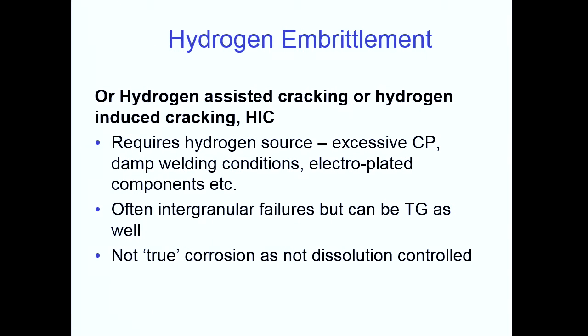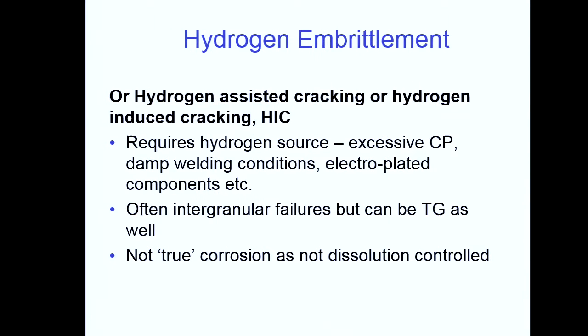And hydrogen is quite a tricky sort of material to deal with. It's colourless, it's odourless, it moves fast through materials, so it quite often gets used as an explanation for odd failures. Clearly, if you've got loads of corrosion product around, then you're at an anodic potential, and so it's not hydrogen embrittlement. But your first question really is, where do you get the hydrogen from?